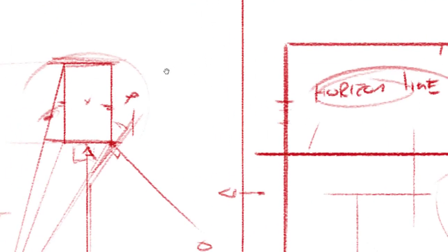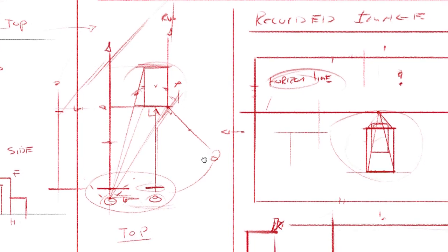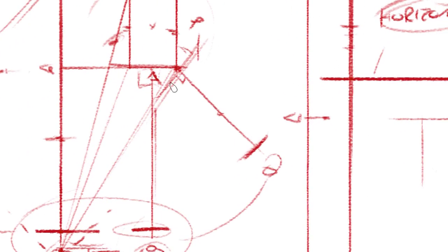These corners. Okay, so now this line actually goes to a right vanishing point, and this line goes to a left vanishing point. Okay, so if this guy is looking straight ahead, and the line of sight eventually is the horizon line, this would actually find a point there. Okay, so let's record this on the picture plane, because this is where we want to see this. So how do I find these vanishing points on the picture plane?